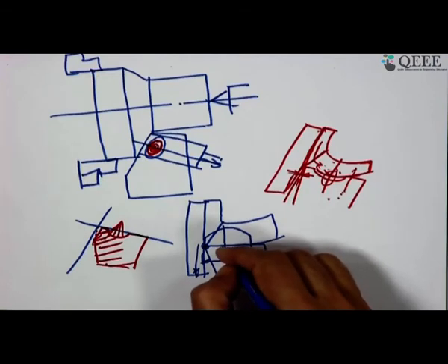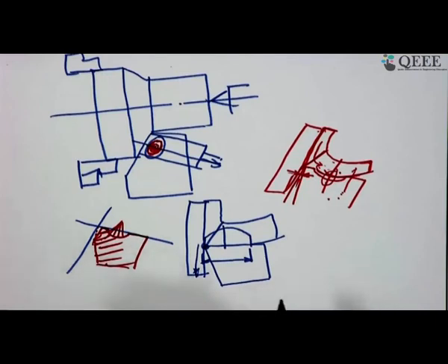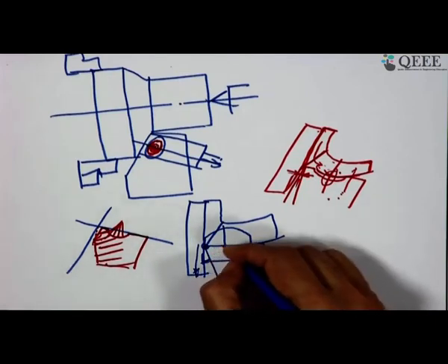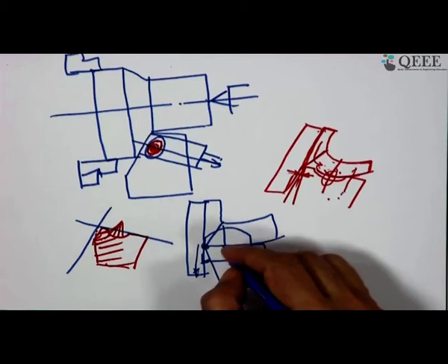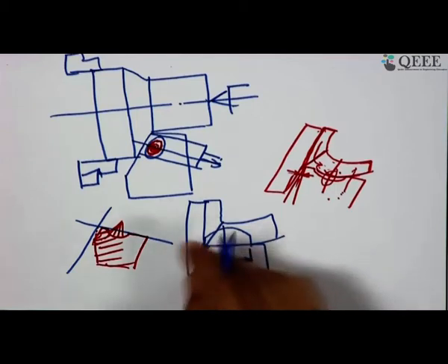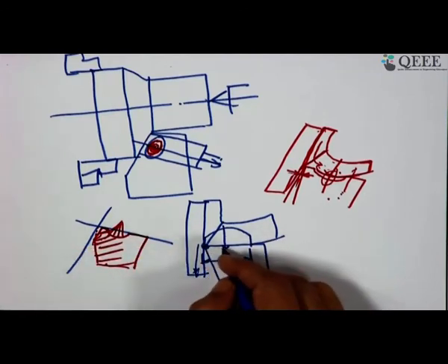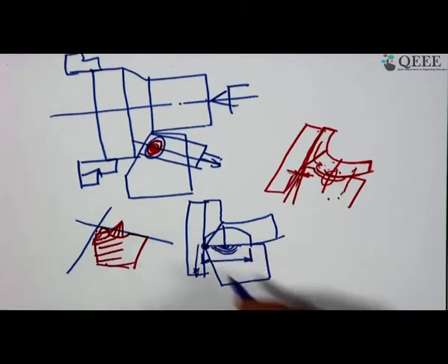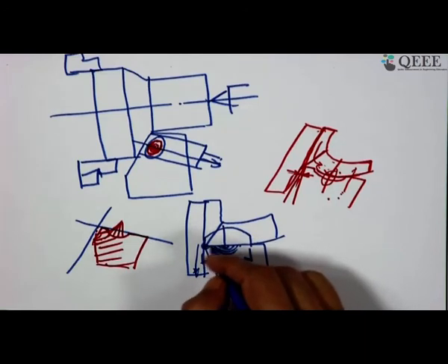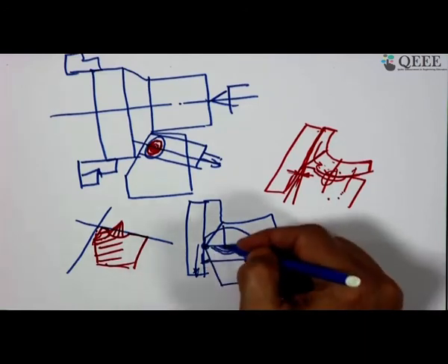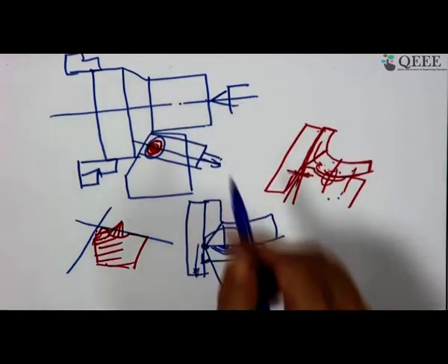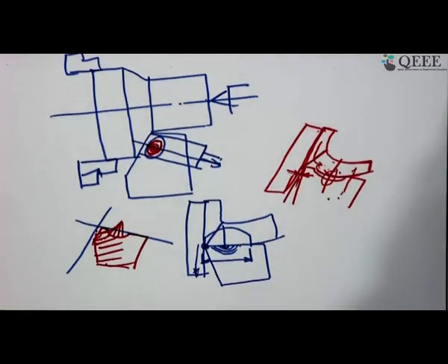That is why you can see the crater embryo, the nucleation or embryo formation of the crater, starts from a point just behind the cutting edge. It is not on the cutting edge, and gradually it spreads on both sides. This is the reason the temperature profile is not only along the direction of chip flow, but also in this direction. These two combine to make this kind of profile.